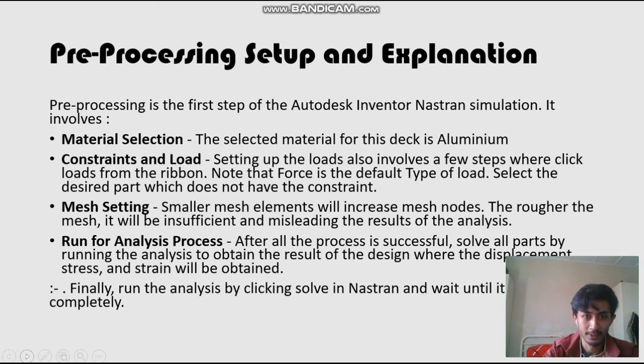The second one is setting up the load, which also involves a few steps; we click load from the ribbon. And the next one is mesh setting. A smaller mesh element will increase the mesh nodes. The rougher the mesh, the more insufficient it will be, and it will mislead the result of the analysis. And the last step is to run the analysis process.